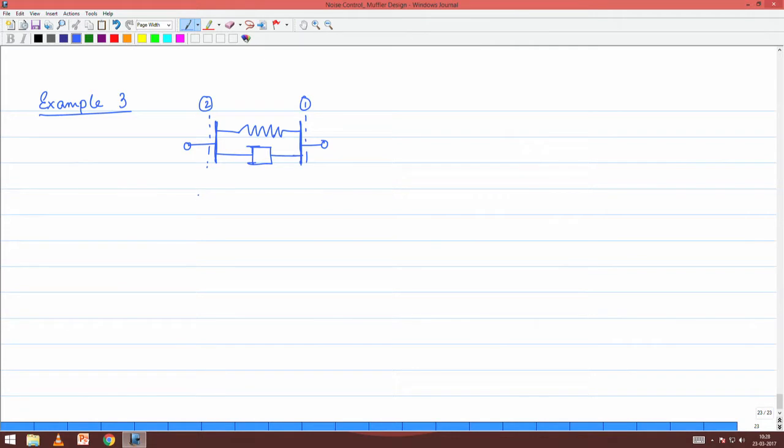Okay. So, at this station 2, the V of the spring is equal to the V of the damper. Similarly, at station 1, the V of the spring is equal to the V of the damper, right. So, at both these stations, the spring element and the damping element have got the same motion, which means that kinematically they are equivalent, right. But will the spring force and the damping force be the same? Not necessarily, right.